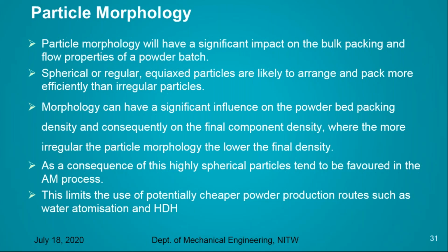If the particles are spherical and regularly equiaxed, then the packing arrangement and the packing ratio will be very efficient compared with irregular particles. The morphology has a significant influence on the powder bed packing density. Morphology is very important for the powder bed packing density of the powder particles, and consequently